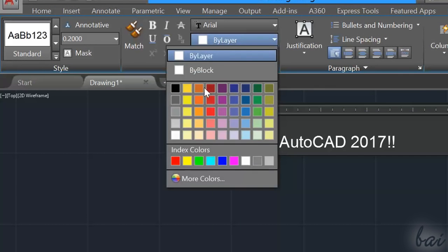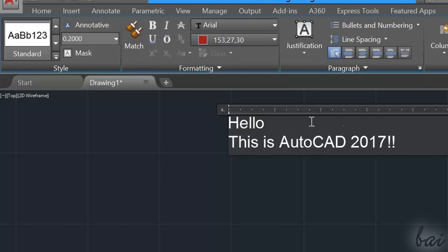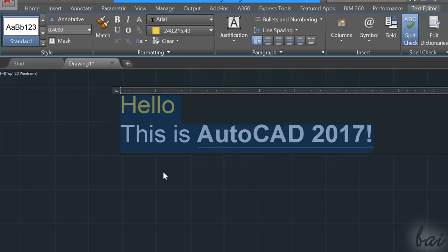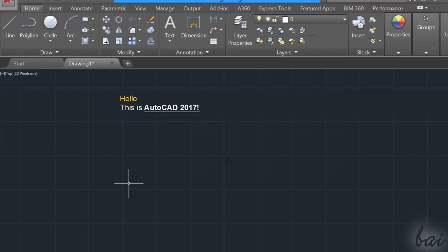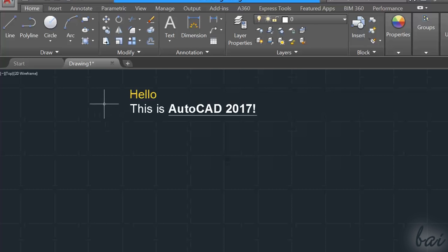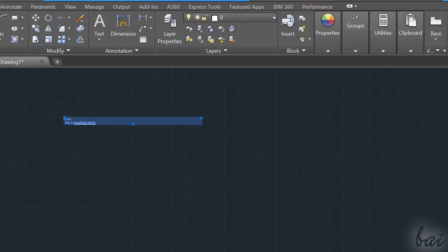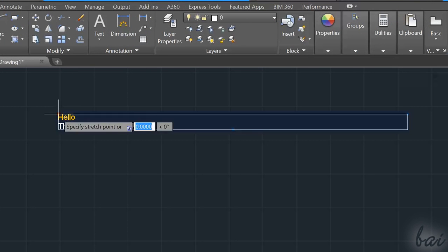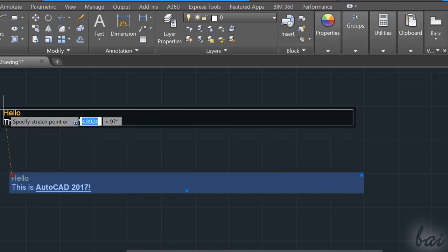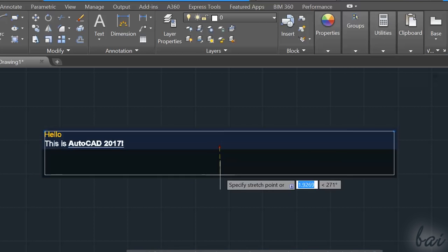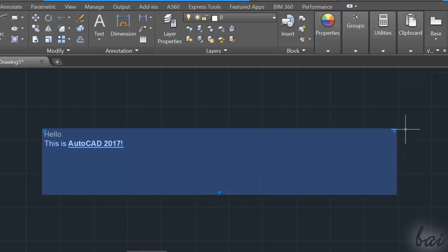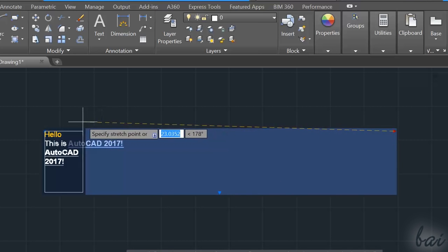Remember to select the text or nothing will be applied. Once text is ready, click outside to close its box. The final text size will be the one defined inside the Style section and not the one seen in the preview. This text will be an independent object that can be moved through its corner node. You can also adjust its text area through the blue arrows. This may change its text distribution.